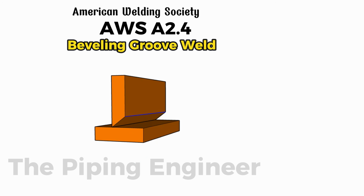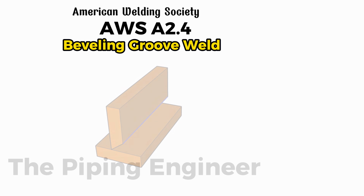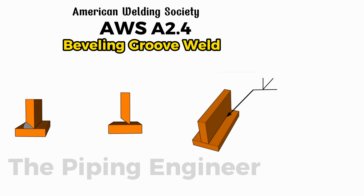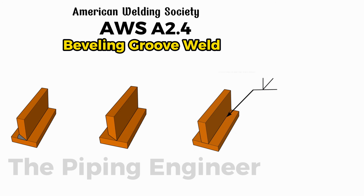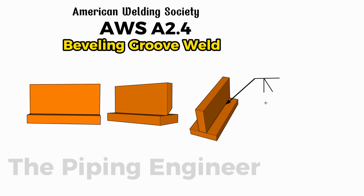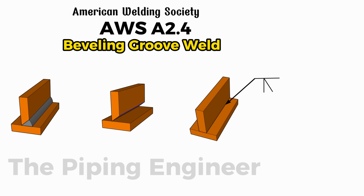Now, let's learn more about welding symbols specifically through the lens of beveling groove welds. Above the reference line, when a beveling groove weld symbol is placed above the reference line, it instructs the welder to perform the edge preparation and weld on the other side, the side opposite to the arrow side, of the joint. Below the reference line, conversely, placing the beveling groove weld symbol below the reference line specifies that the beveling and welding must be executed on the arrow side of the joint, directly facing the pointer.